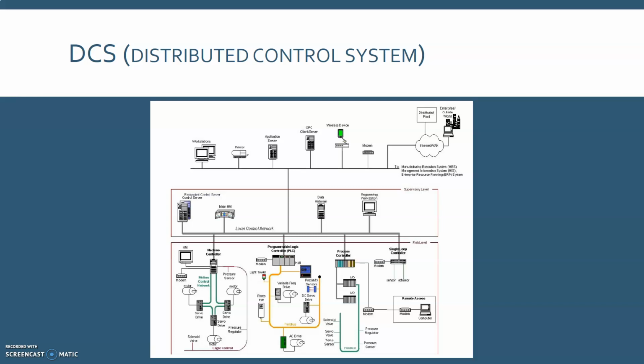In this example, the supervisory controller, that is the control server, communicates to the subordinates via the control network. The supervisor sends set points to and requests data from distributed field controllers, and the distributed controllers control their process actuators based on control server commands and sensor feedback from process sensors. The field control devices shown include a PLC, a process controller, a single loop controller, and a machine controller.